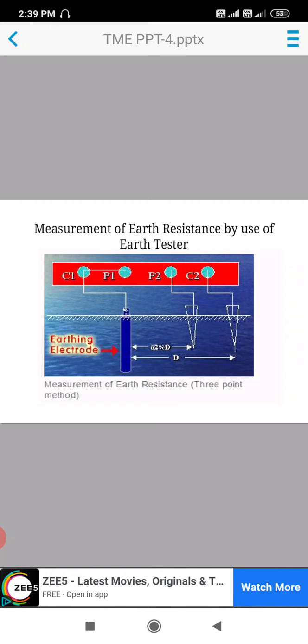Then we rotate the handle of the earth tester at a specific speed, and we get the earth resistance at that point. Next, we change the position of the potential electrode, take 4 to 5 readings, and take the average of those readings, which is the average earth resistance of that area.